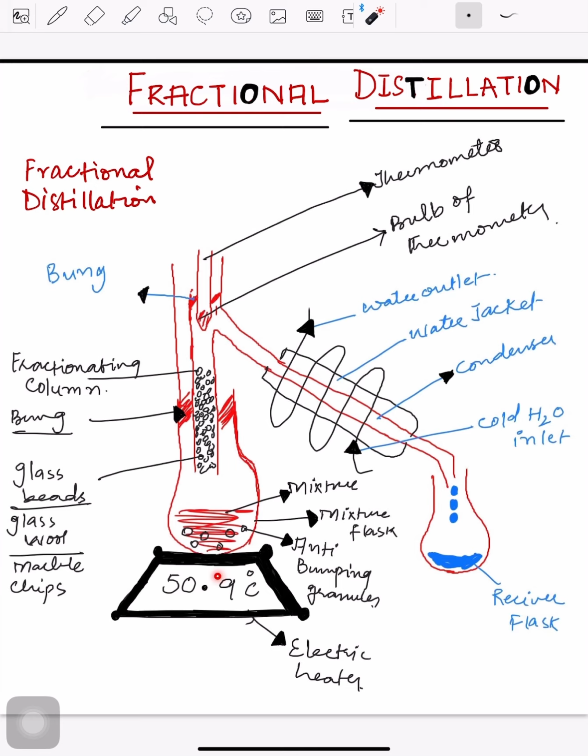It is an instrument which is used for controlled heating. So for example, if I would like that temperature must not exceed 60 degrees Celsius, then I will adjust the thermostat on 60 degrees Celsius, and the temperature of the electric heater will not exceed that. So due to all these reasons, a controlled heating, a uniform smooth heating, so that fractions may not catch fire, due to all these reasons, we are using this electric heater.